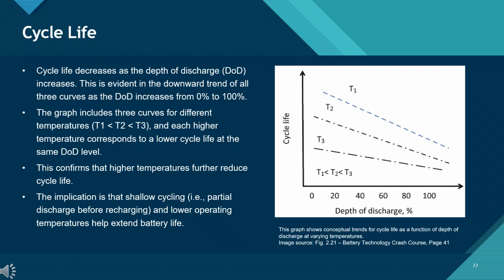To extend cycle life, it's best to use shallow cycling, charging before the battery is fully discharged, and to operate at lower temperatures whenever possible.